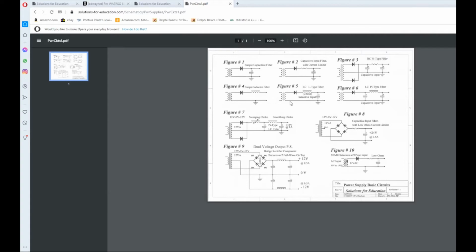whereas the coil simply resists surge values and helps the capacitor charge up. Now, one of the things that we learned a long time ago is if you're building a power supply for a transmitter, we found that this approach is better than this approach or even this approach, because this coil that's in here tends to smooth the current issues out under heavy current draw. So you'll find the people that build up their modulator circuits for power supplies followed this principle because of the limitation of that surge current.